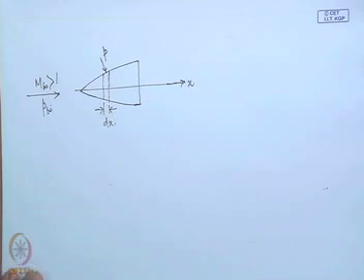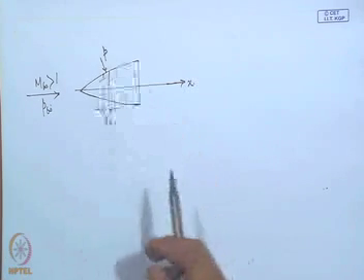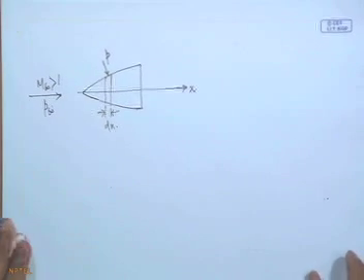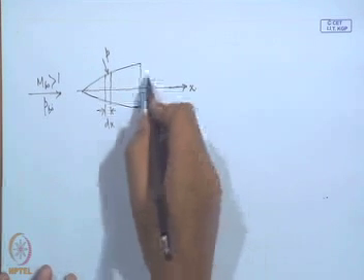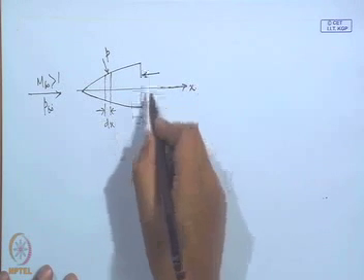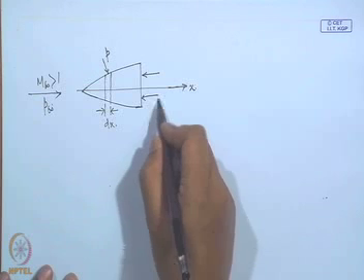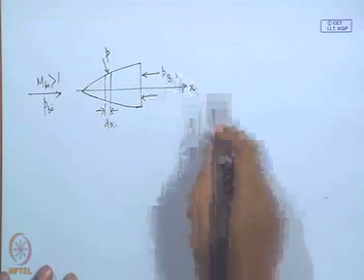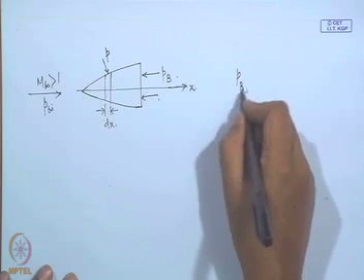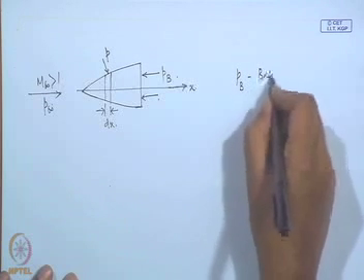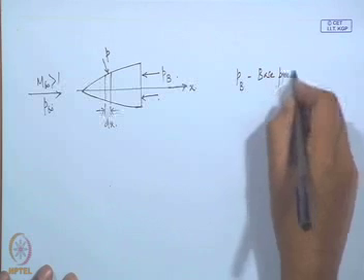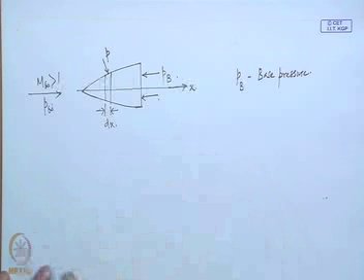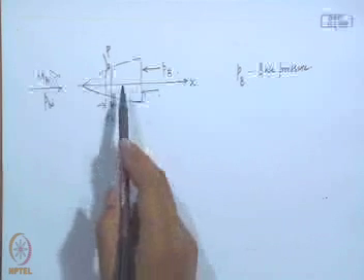The pressure here is P infinity, the pressure on the surface is P. At the back the pressure will of course be different, and we will call that base pressure. Now, the pressure coefficient that we have obtained corresponds to this pressure.